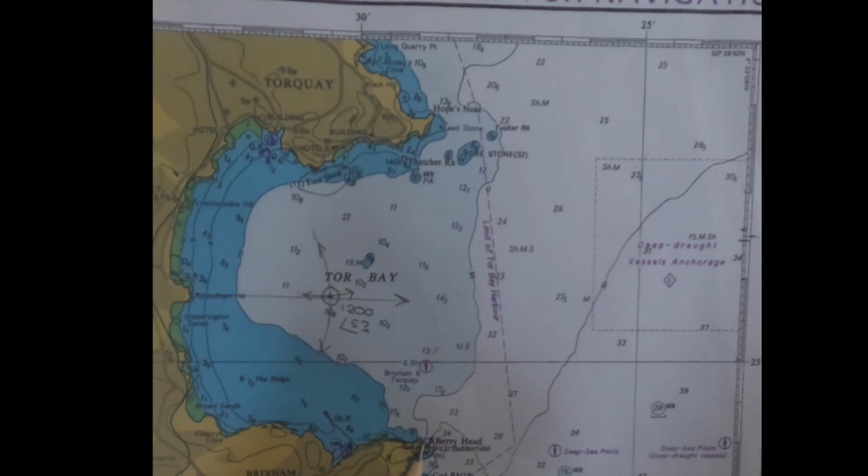It'll be in the manual, but most leisure radars will be about 5 degrees, so we need to move them in about 2.5 degrees. If it's a spot on point or a buoy, we can take that straight away and just pop the line on and give our position. Okay, it's really easy to do, and also it's from an independent source.